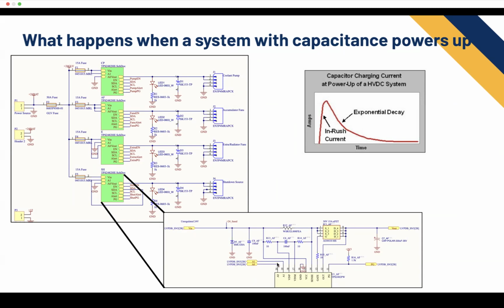So what the eFuse has is called a timer pin. And actually, I realized I forgot to put a screenshot. It's on the bottom of the chip. I only have a screenshot here at the top half. But the chip has a timer pin where it's able to slow that inrush current and slowly open up the FET instead of instantly pouring everything in there. And that resistance allows you to charge a lot more slowly and approach the actual voltage that you want. So basically all of that is to say you insert a resistance to slow down your charging.